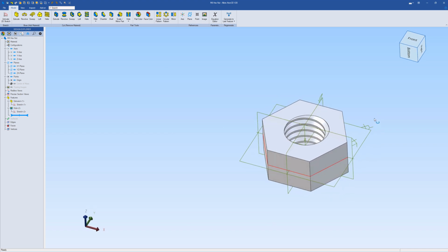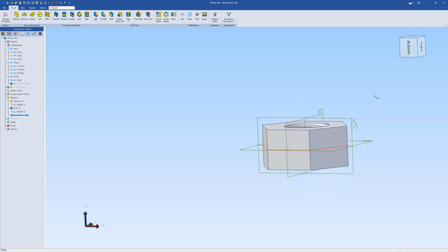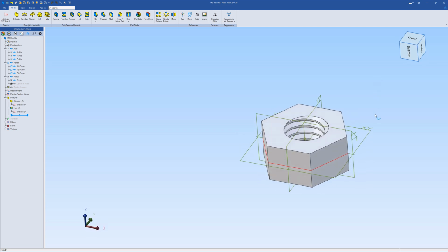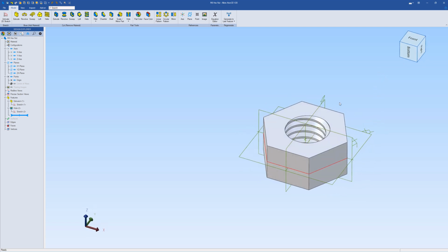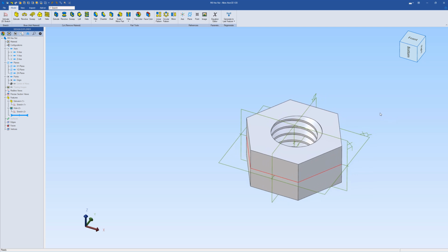to the nut. Now the other thing I need is a chamfer lead in and lead out at the other end. Now on the hole tool I could have used a countersunk hole to achieve this, but that would only allow me to have a lead in on one side of the hole. So instead I'm going to manually revolve a cut to create a lead in one side, and then I can mirror that so I can have a lead in both sides of the nut.